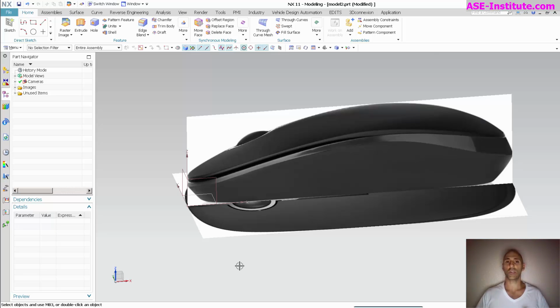A lot of times you're going to get sketches, whether it's a car, product like this. I do a lot of product design for various corporations. If you look at my website, you'll see I do work for Black & Decker. I've done work in the past for people like Consolidated Container. And what you do is you import an image. Some really talented stylist goes out and starts sketching out an image, and they hand it to you, and you have to make sure you have the correct size, especially for a container or a power tool or things of that nature. You need to make sure it's scaled to the proper dimensions. And this is how you go about taking that image, bringing it in, scaling it to the proper dimensions.